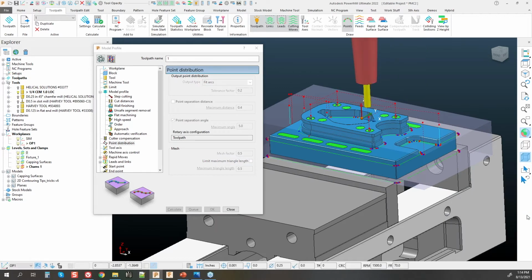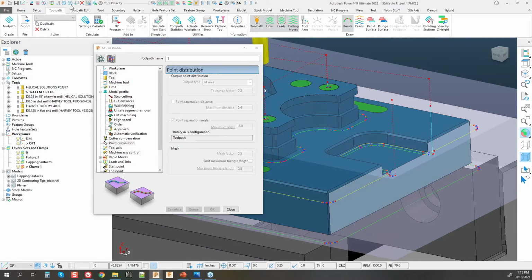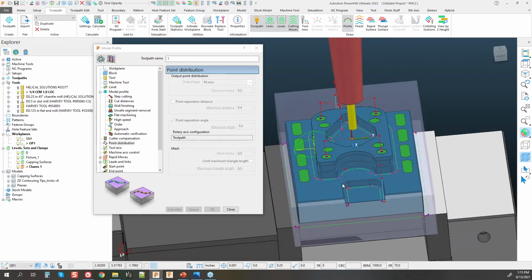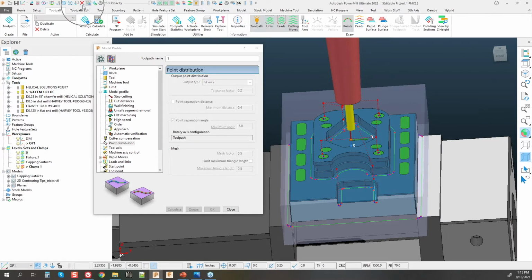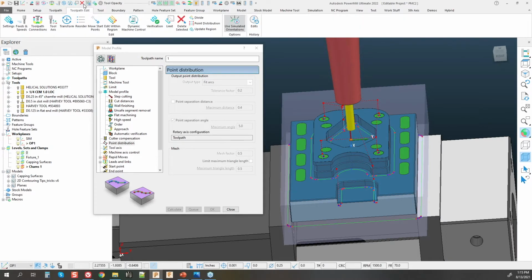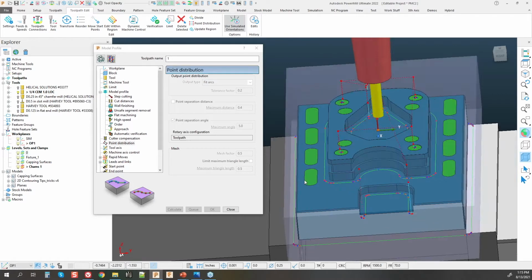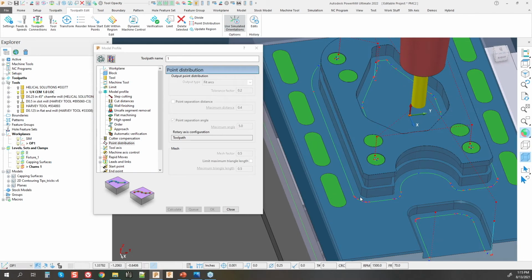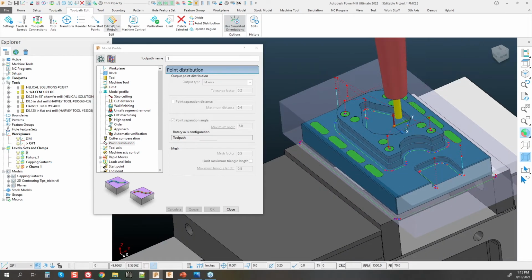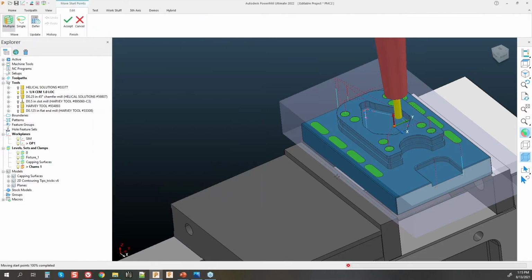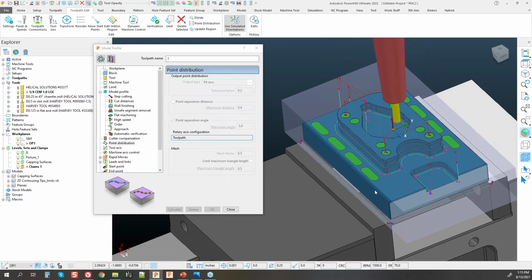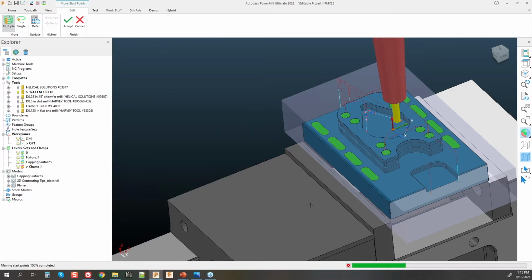Now, again, because we can go back and adjust features so easily in PowerMill, that's how we learned things a long time ago, to go back and we can edit features, or we can just delete toolpath that's unnecessary. In this case, I don't really need that pass that's up above on that top. So I'll just select that, come up to my quick access toolbar up here where I have delete set up, my toolpath edit capability, and just delete what I don't want there. As long as that point spread is correct, I'm pretty well ready to go. Start and stop points, it's the same thing. If I come to the edit toolpath, I can move start and stop points for any given toolpath anywhere that I want and apply a new start point to it. Oops, I forgot to cross through the toolpath there.